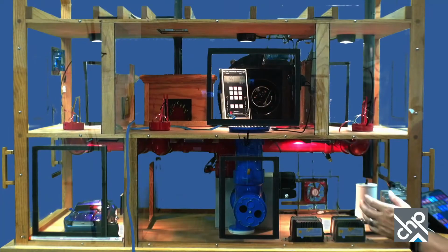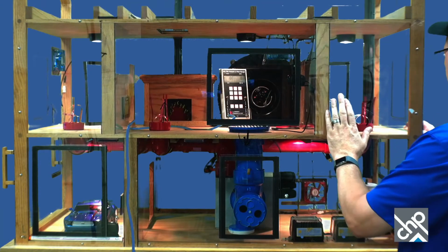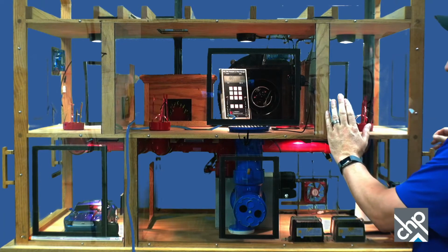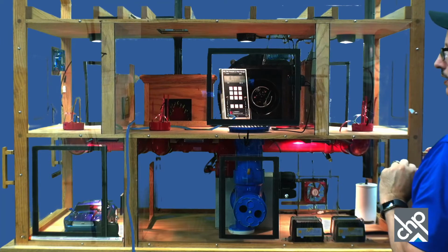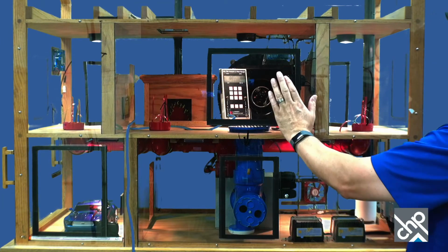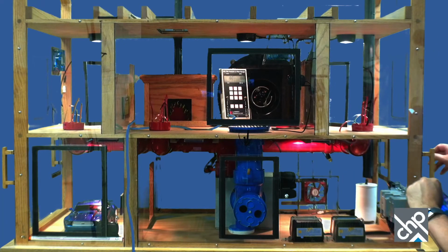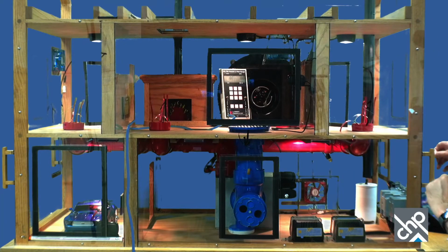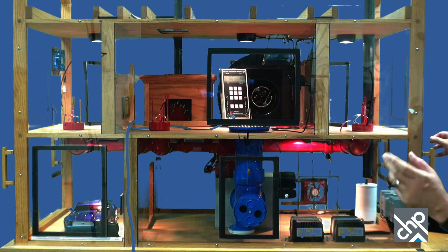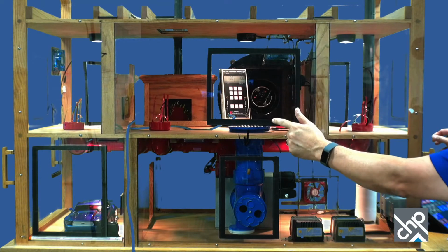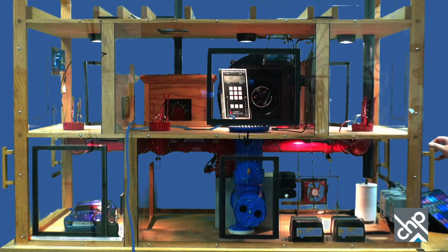So right now, I'm going to reach in here. The bedroom door, I got, like I said, my little string right here, so I can close this door. So we're going to watch what happens to the pressure in this main part of the building here. And we'll watch the pressure first, and then I'll do it with smoke. Maybe that's the way we'll do it. So I'm going to close this, and you think about what might happen, because now we got air that can't get back to there, so this return is going to be looking for it, almost like when we had a supply leak, okay? See what happens.